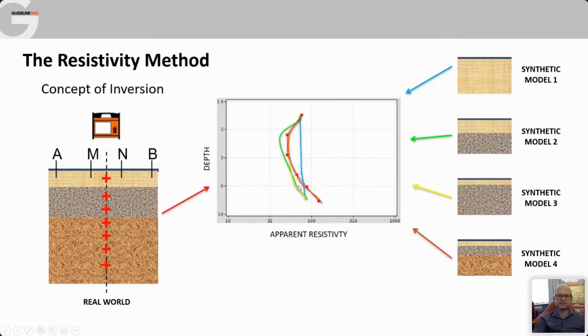And at the end of that process, the software will give us what we call a residual, and the residual is an indication of how close that model data is to the raw data that we've put in to start with. And it's normally shown as a percentage, and the lower that percentage, theoretically, the better. So low percentage would mean that the model data is tracking the curve from our instrument very, very closely.